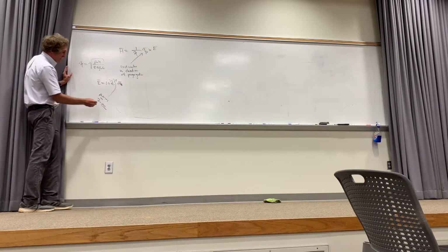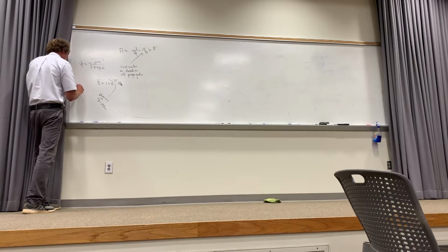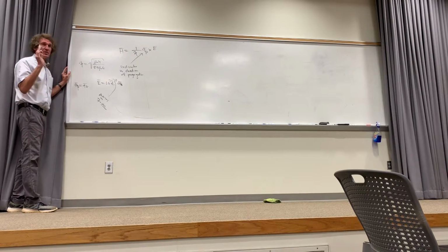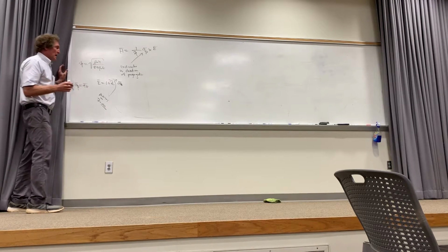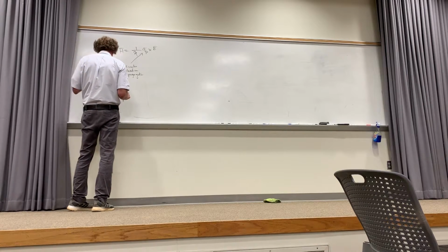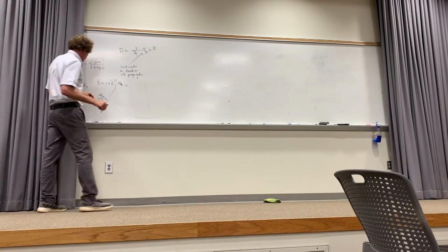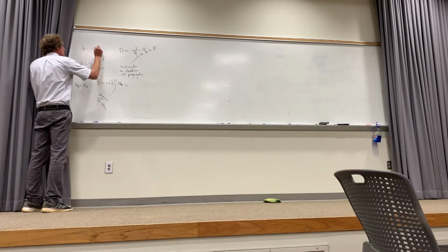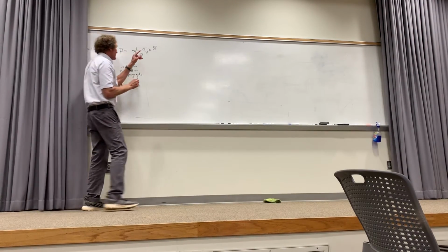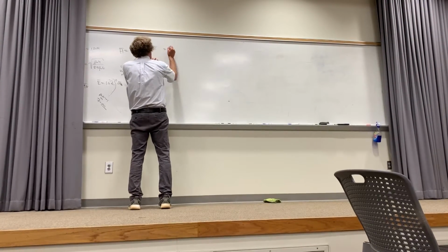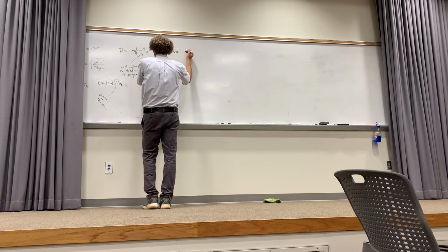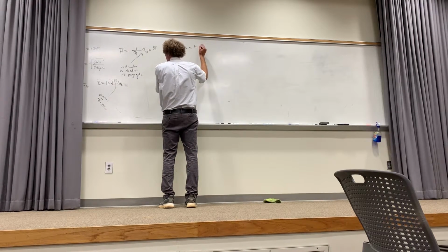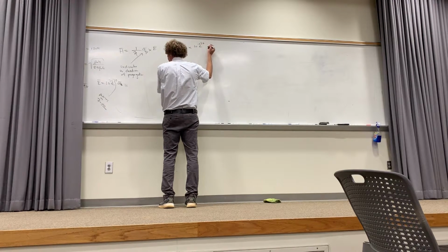Do you all follow me? So that means if it's moving in the z direction, that a_P, the propagation vector for this, would be a_z. It's a unit vector in the direction of propagation. Do you all follow me? Now, it's got to be a unit vector, magnitude of 1. Then it's crossed into the actual E field. Let's assume that eta is just 120 pi ohms. I've got the direction of propagation, the E field, and eta. So that means it would be 1 over 120 pi times the unit vector in the direction of propagation, a_z, crossed into the E field, and the E field would be 10 times e to the minus j3z a_x.